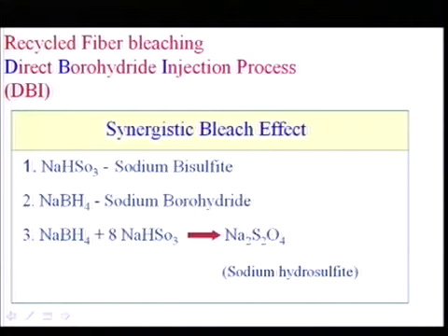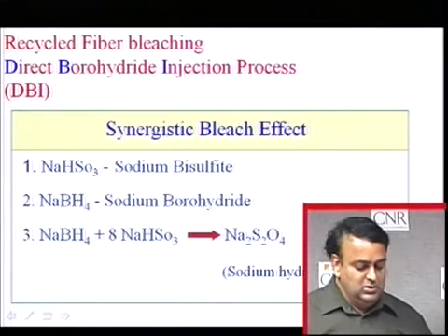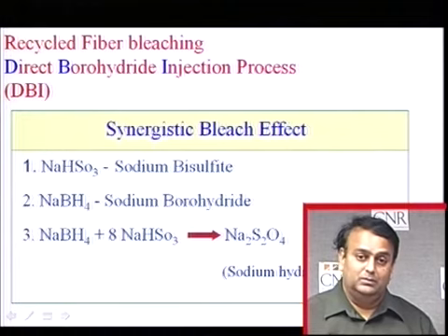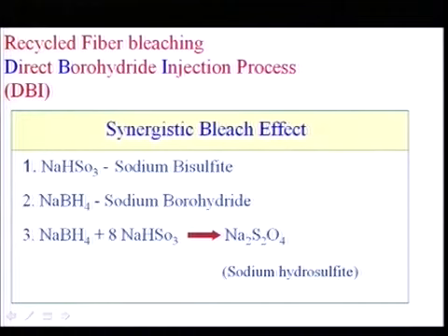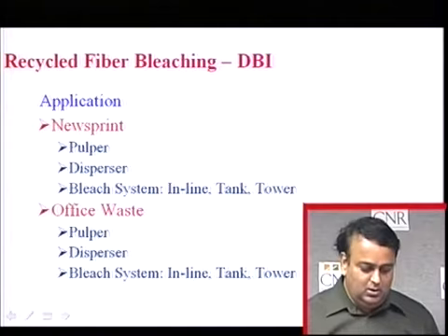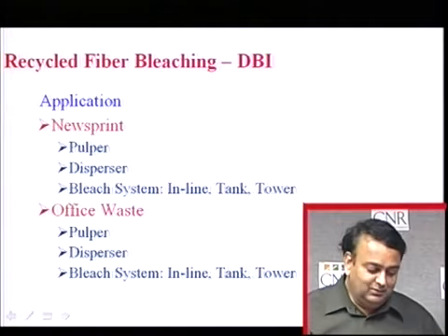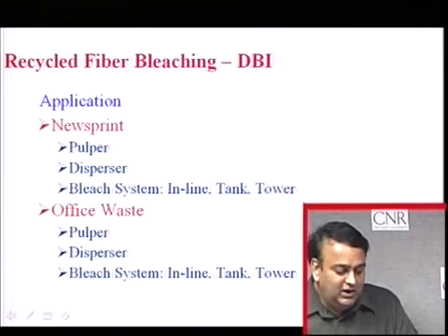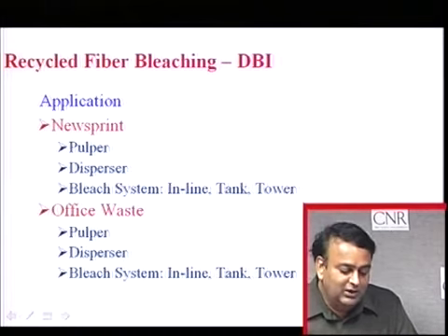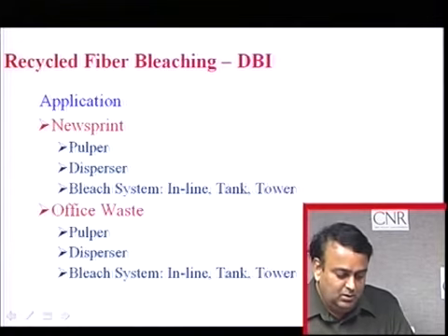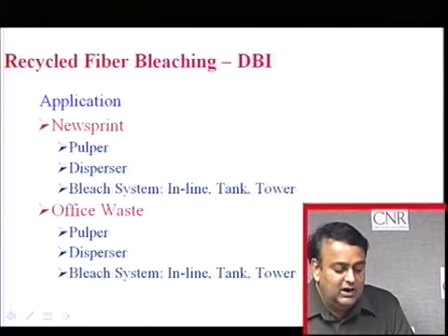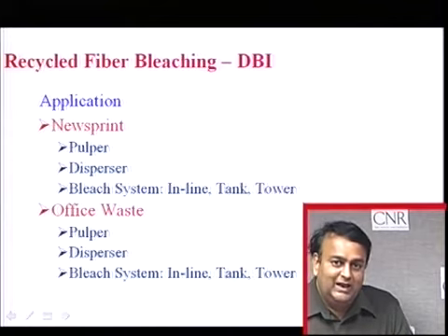When you mix these two chemicals, it forms sodium hydrosulfite, and sodium hydrosulfite is a moderate reducing chemical. So you have a mild sodium bisulfite, moderate sodium hydrosulfite, and powerful reducing chemical sodium borohydride. Now, where do you apply these chemicals? In a de-inking mill, it can be applied in the pulper, disperser, or inline, tank, or tower for both newsprint and office waste, for working on lignin or working on dyes.